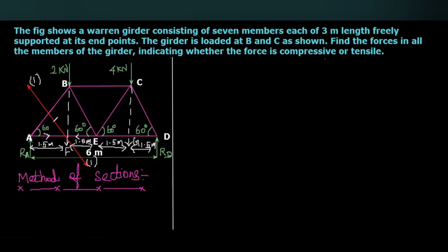And even in the considered portion, the whole member, that means here there is no whole member. I will show you when we discuss the other section line. Even in the considered portion, if you have any whole member which is not cut by the section line, the forces in that particular member you don't want to consider.